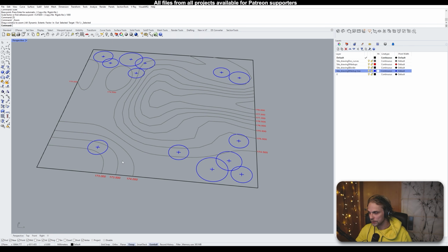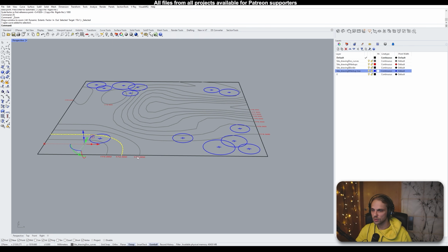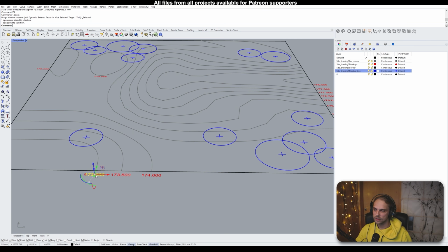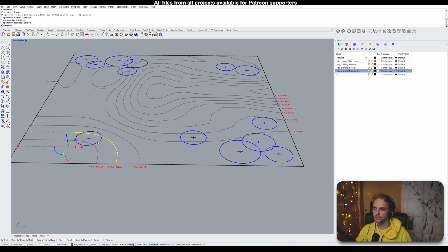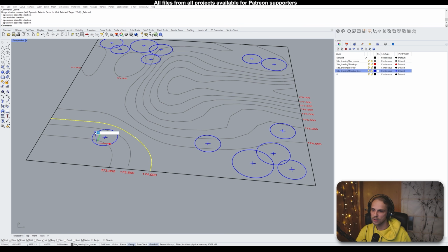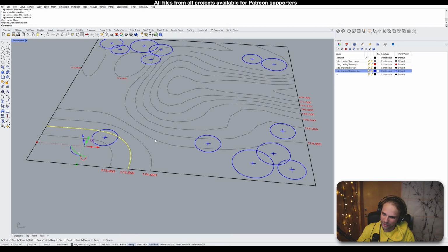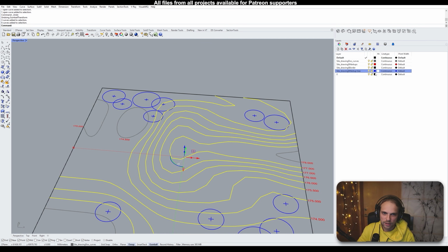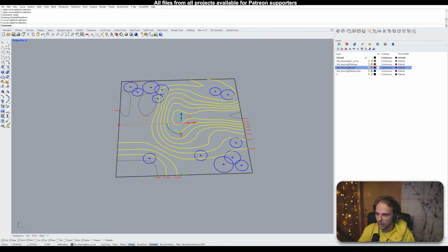So where were we? We were lifting up our contour lines to the correct height. Well, again, the lowest curve is going to be 500 millimeters higher. 174 is going to be 1000, or rather, sorry, let's go back. It's much better if you select all of the curves, and let's lock the tree and the markups layers and the side border layer, so that we don't accidentally select them. I'm just in the layers menu locking those.